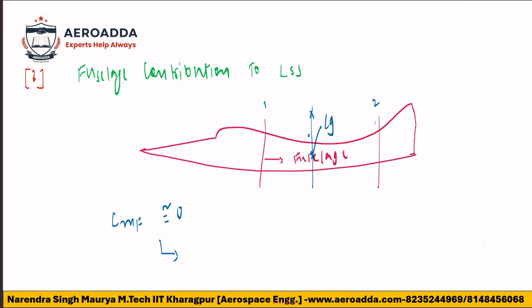So even the fuselage has that shape, so that it can reduce drag, but because it is floating, a little bit of lift is generated. That lift force times the distance between CG and the aerodynamic center will be very less, so the moment produced is very less.